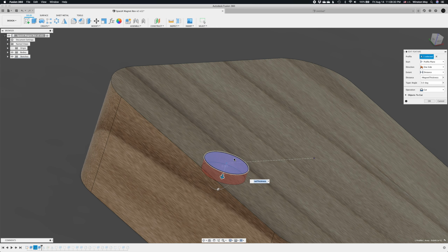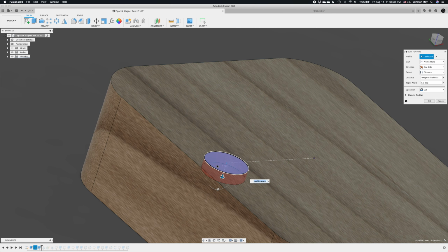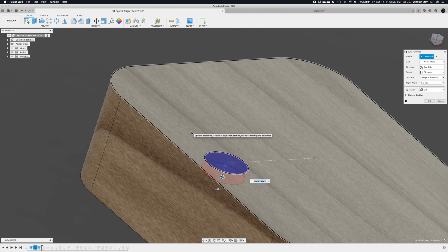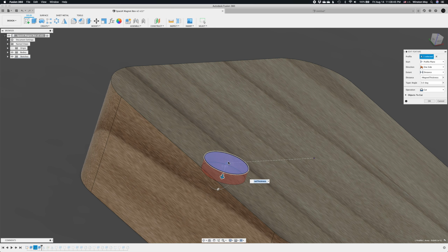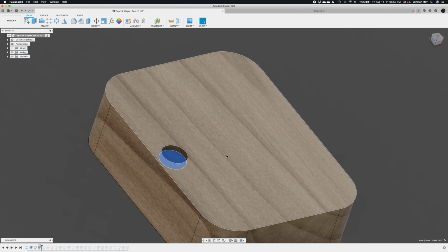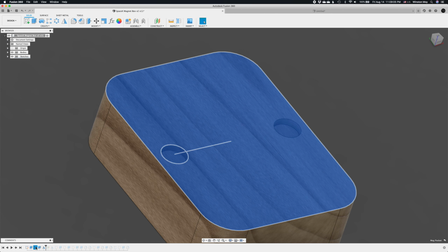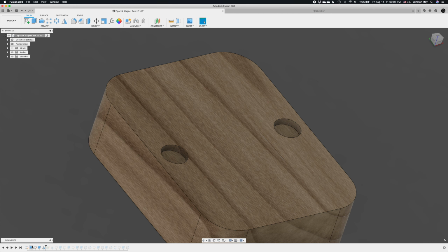And if you have a bubble of CA glue or something and you don't push the magnet in all the way, the magnet's not going to be proud of that surface, and the box halves will still be able to close seamlessly. Plus, the further away these magnets are, the weaker the attractive force is, so you can actually tune the force it takes to pry the box halves apart. So I like to just go a couple thou deeper than the magnet actually is tall. You could go even more aggressive, but then you'll have a little bit more of a reveal of this sidewall above the magnet. I will just mirror this feature. I could have just drawn 2 magnet holes, but mirroring that extrude was just as easy, and I was lazy.